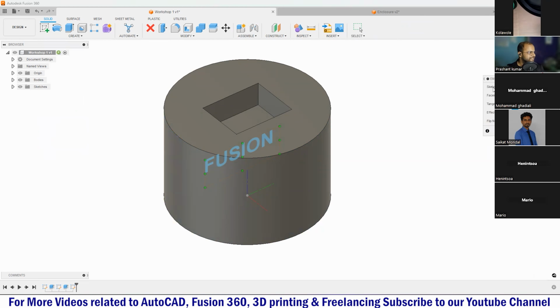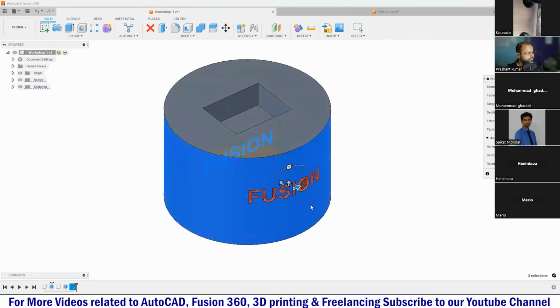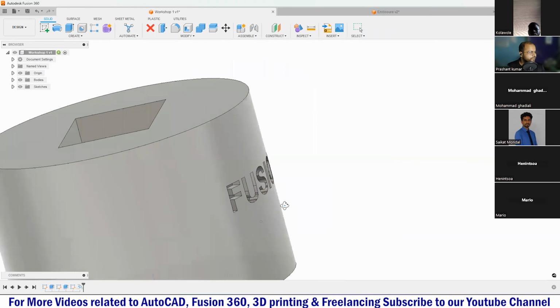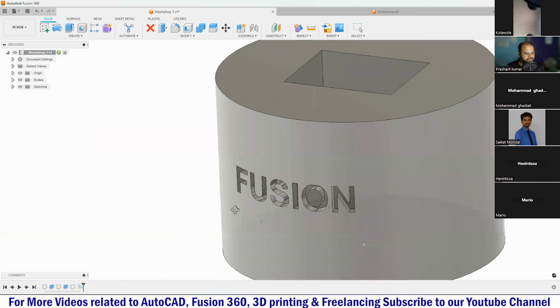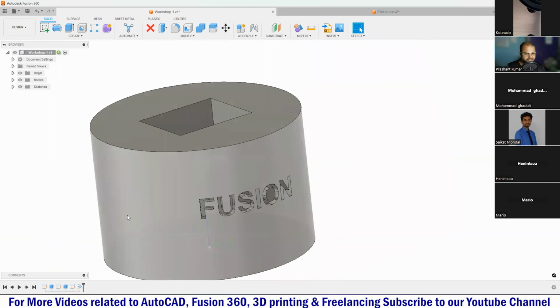The first thing it is asking me is to select the profile. Definitely this sketch is my profile. Then the face on which you want to emboss. So this is my face. And whether you want it extruded from the face or extrude cut from the face. I will make it extrude cut. And the moment I press OK, boom, we had just created something embossed on our curved feature like this. It was really easy.